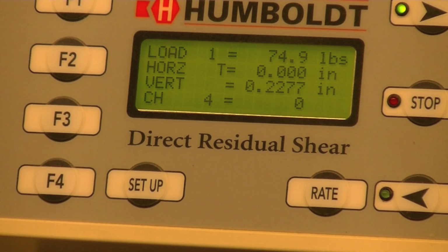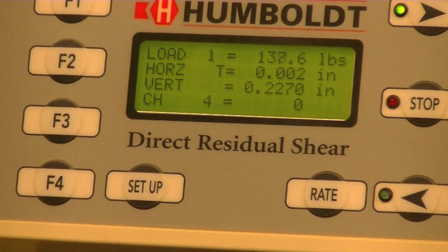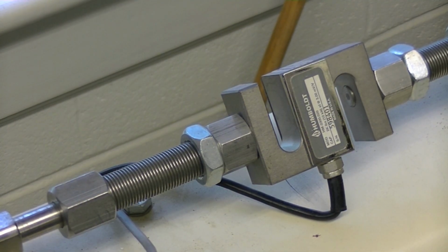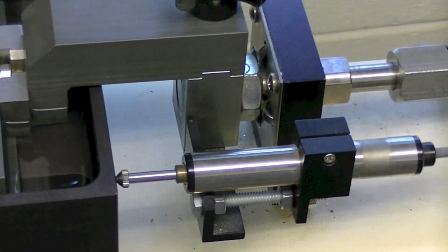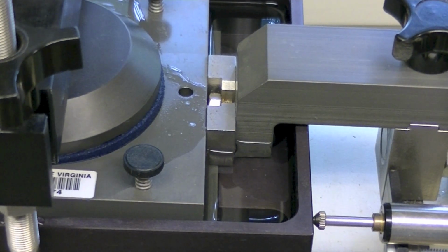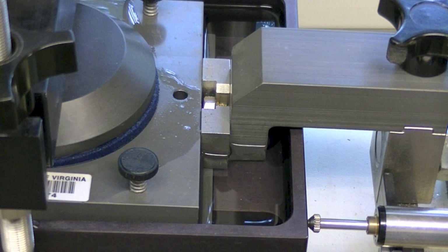Notice that loads increase, load 1 in our case, and horizontal deformations, HORZ1 in our case, increase with it. Shear the sample to a strain of 10% relative to the diameter of the sample. Failure will occur on almost all soil samples at 10% strain relative to its diameter size. Once 10% strain, 10% deformation relative to that of the specimen diameter is achieved, the run can be stopped.